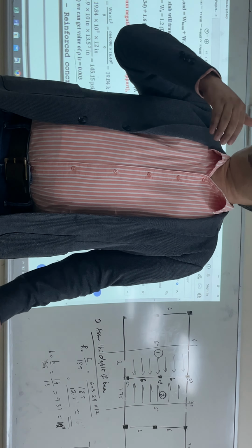If you are a very good designer, you will find the area here with a different diameter here, a different diameter here, to choose the specific value. Then practically it is impossible to do all these things, because with 4 reinforcement bars of different diameters, a congestion of steel will take place, the proper concreting will not be done, and your strength will reduce.